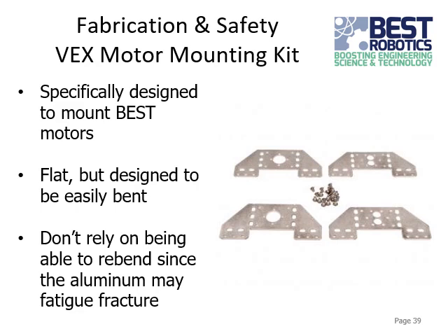Just put it in a vise or something on a straight edge, and just bend it around the corner of that straight edge along those lines you can kind of see along them. Don't try to rebend these because they're only designed to be bent once, really. So there's kind of two different options. You could mix and match a little bit, but the two main ways of bending these